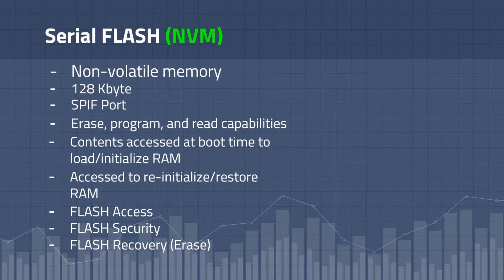The flash data can be made secure for the boot process. JTAG or Nexus interfaces start out disabled. The bootstrap then determines if the flash is secure. This is done using the first 4 bytes of the flash, which are reserved for the validation word. If the validation word is OK, then the data is valid, but not necessarily protected. If the validation word is SECU, then the data is both valid and secure.